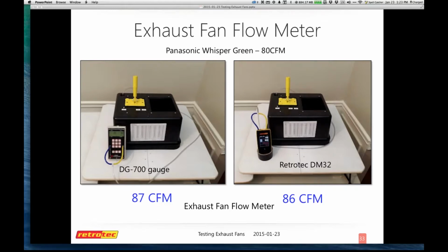So the exhaust fan, my keyboard is very sensitive. The other one is to use a device that actually can handle either flow. This one here I showed you just to compare what the numbers were. This is the FlowFinder, and here it's upside down in terms of how I use it as the demonstration. But this is as simple as covering the fan and hitting one red button for a brief second, and it does it automatically. The fan itself will match pressures and determine your CFM. And it can do numbers that are incredibly low, or again, it can definitely handle most of the needs we have. It does not do commercial applications at this moment.